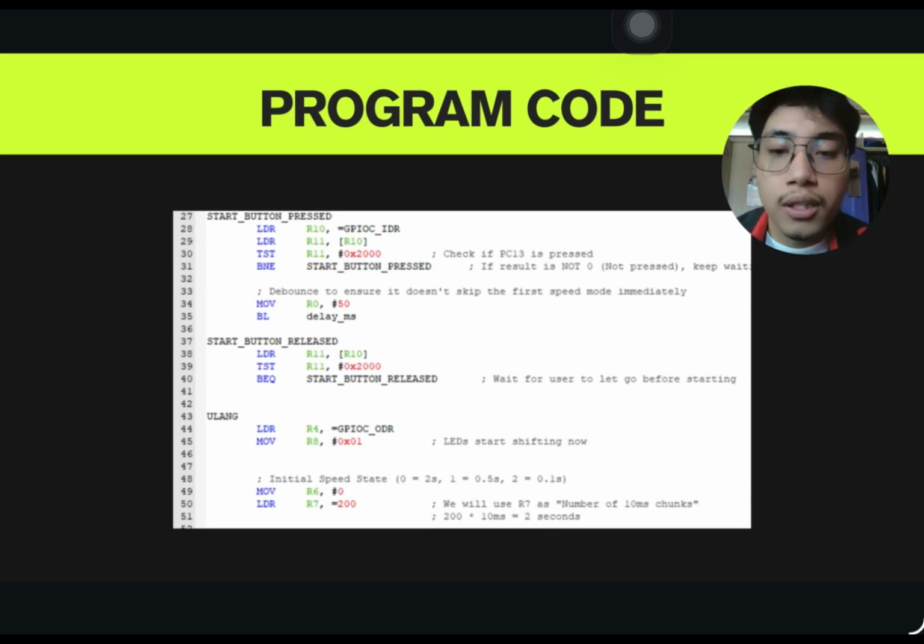So after the button has been released, it will go to the main function ulang, where we load the output into R4, and then the value of R8 is moved to 0x01. So at this point, the LED has started shifting. So for the initial speed state, there are three states that we have declared initially. So 0 is 2 seconds, 1 is 0.5, and 2 is 0.1.